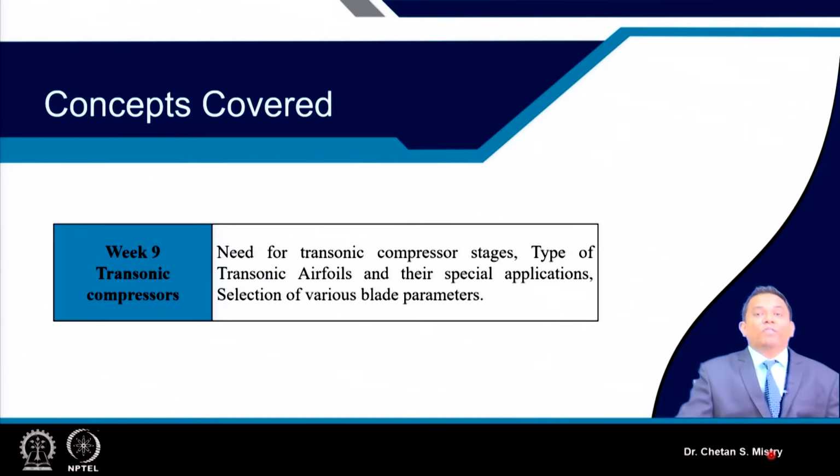Now when the flow at the entry is supersonic, or maybe slightly on the high subsonic side, the initial flow will be followed by a passage shock, which we can treat as a normal shock, giving subsonic flow downstream. The change of flow properties from supersonic to subsonic because of the presence of a normal shock gives us a very high pressure rise, and that is what we take as a benefit, which people have explored after the 60s.